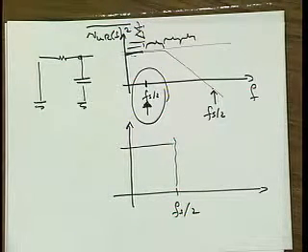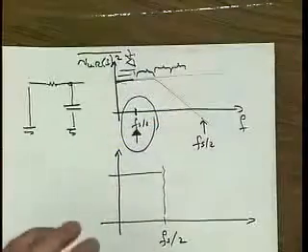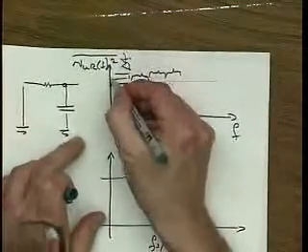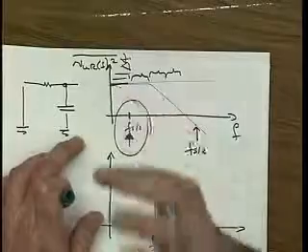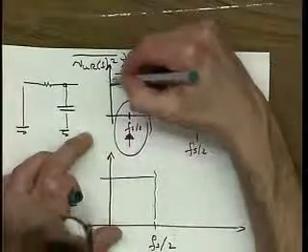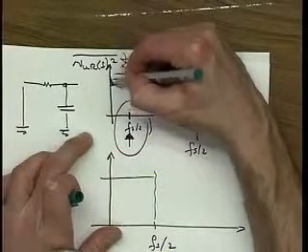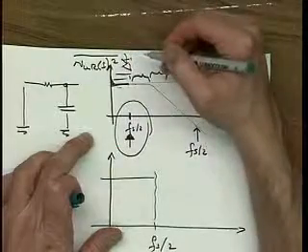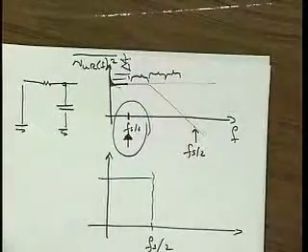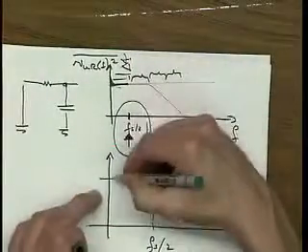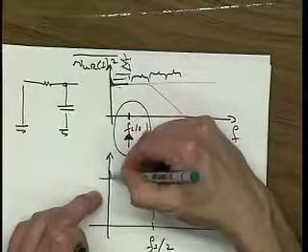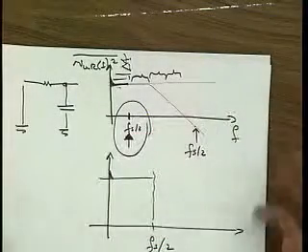There is one exception, and that is if here, of course, we had 1 over F noise, then now you need to use your microscope because my F is too small. Then this 1 over F noise was down here, right? There's a little sliver down here. Well, there is just no aliasing happening with that at all, and so that just plain shows up here again, right?